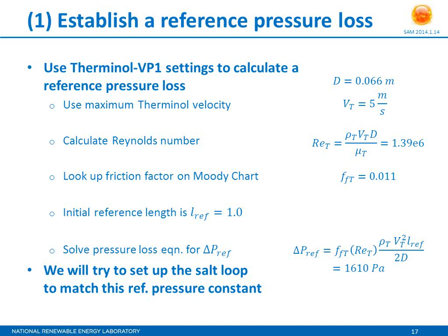There's one other question here. How do we estimate the losses? Maybe I can get clarification: the thermal losses in the field, is that what they're looking for? Not sure if it's that or the parasitic losses. Maybe we'll get a follow-up here. Okay, well, the answer to both of those quickly would be: in the field, we don't estimate, we actually calculate the losses based on heat transfer relationships or detailed heat transfer models. If you're looking at the operation of the field, we model the temperature of the fluid as it passes through.